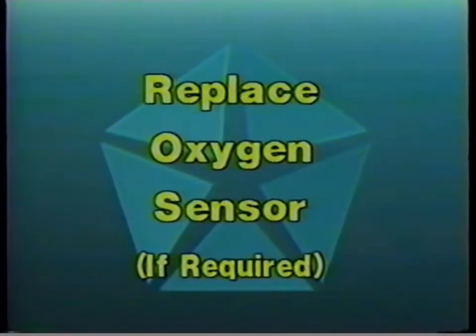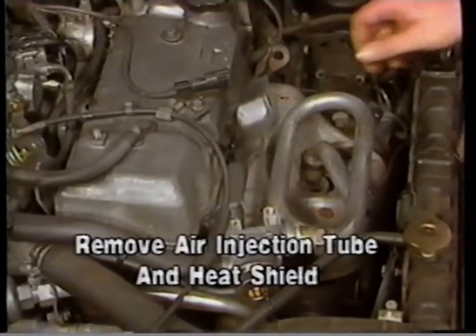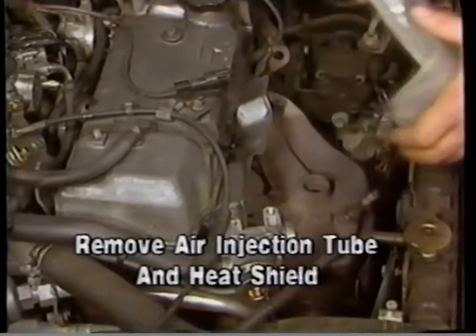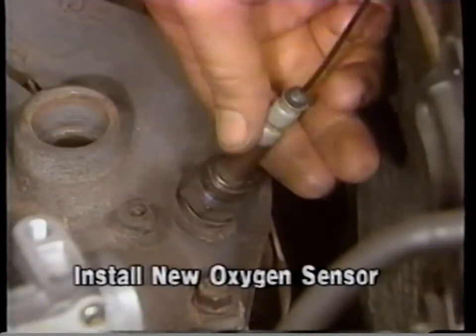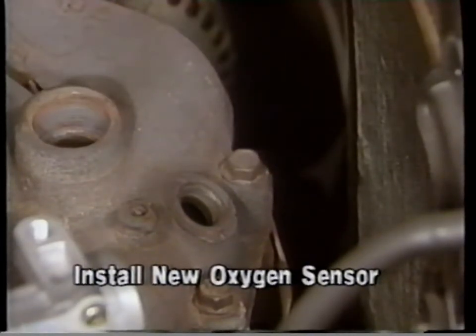At this point in the procedure, the exhaust manifold should be sufficiently cooled down to allow the installation of the oxygen sensor. To do this, disconnect the oxygen sensor electrical connector, remove the air injection tube, and remove the heat shield from the exhaust manifold. Remove the original oxygen sensor from the manifold and set it aside for return to the Warranty Material Return Center.